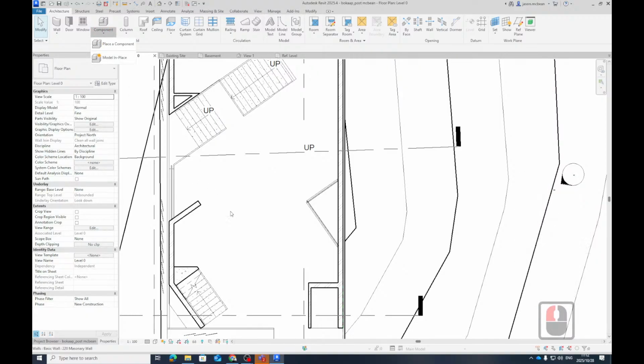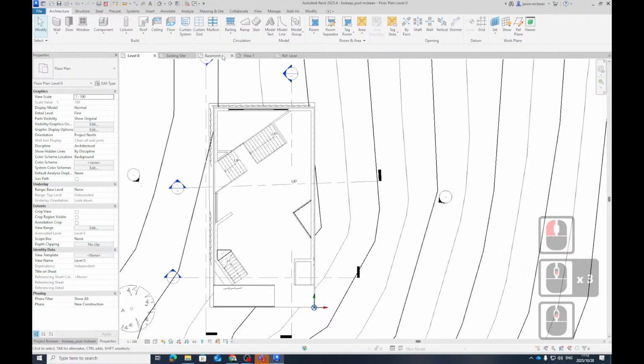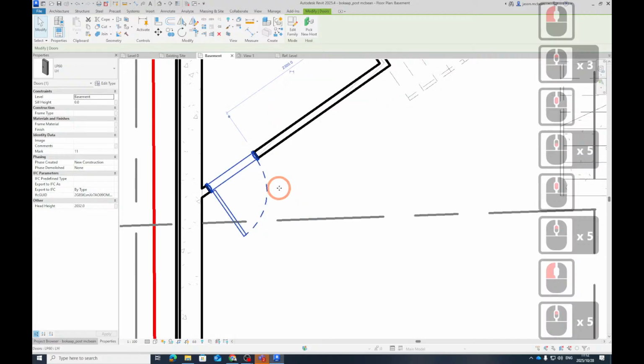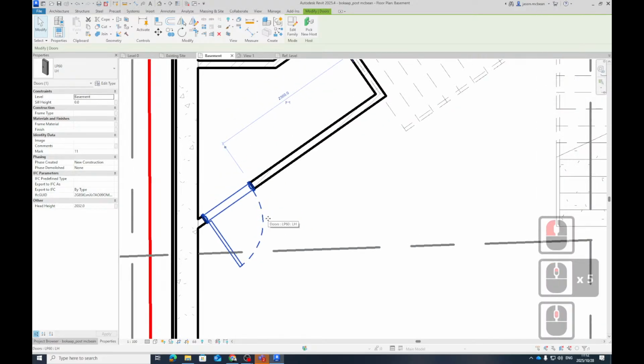and try and do it that way, because to try and write a family, this has always been the problem with Revit. ArchiCAD, to a degree, has the same issue. To go and try and write this thing to behave a certain way, it's a whole lot of work. I'm not lying, sometimes it's 2 weeks to build that family correctly. Constant testing, trying it, bringing it in, it must cut automatically, there are all these parameters, but you